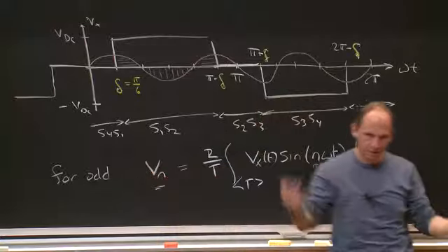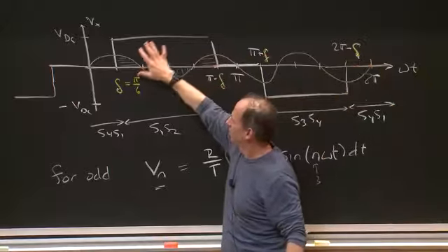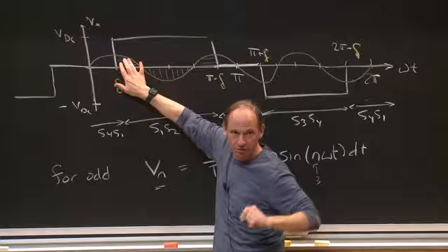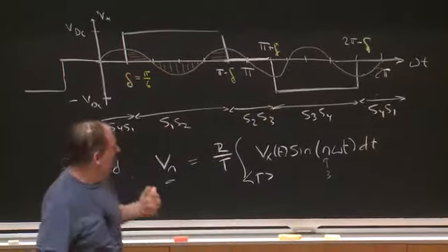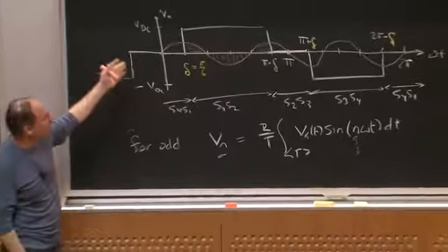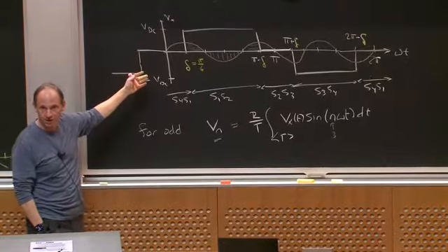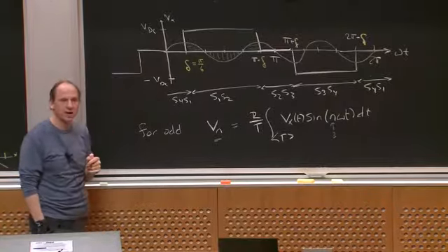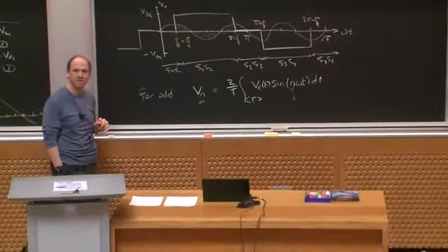So I can look at this waveform and say, if I pick that angle just right, the overlap with this sine 3 omega t is such that I kill the third harmonic. This kind of trick we're going to see we can expand in multiple ways to give us higher performance. But before I go on, is there any question about how that arises or anything up to the present point? That's the quick review of last lecture.